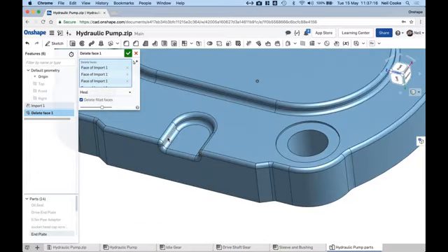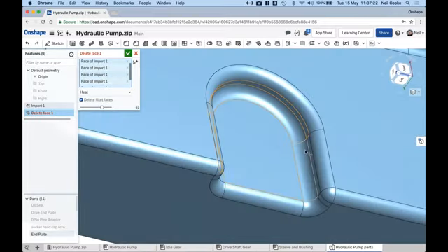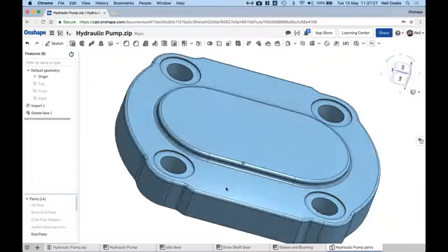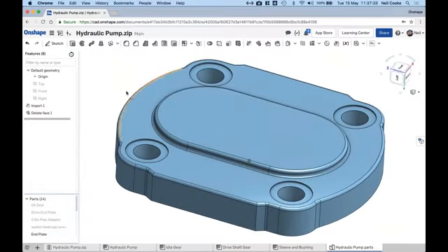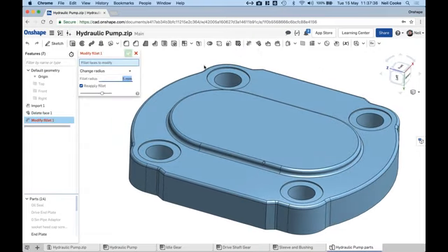And you can do the same on the other side just by selecting those pieces of geometry. So very easy to do to remove geometry. You might also want to change a fillet size. So the modify fillet, which is available in Onshape. SolidWorks can do some of this direct editing, but modifying a fillet is one of the things it can't.